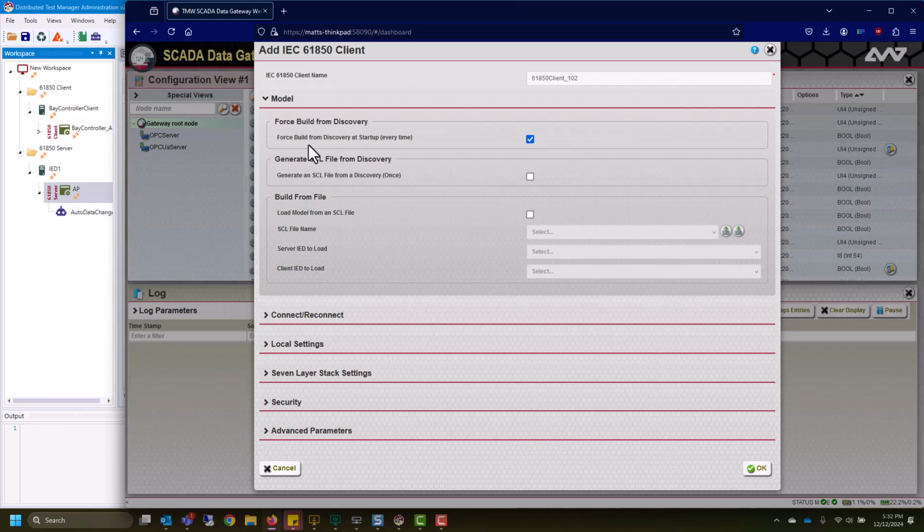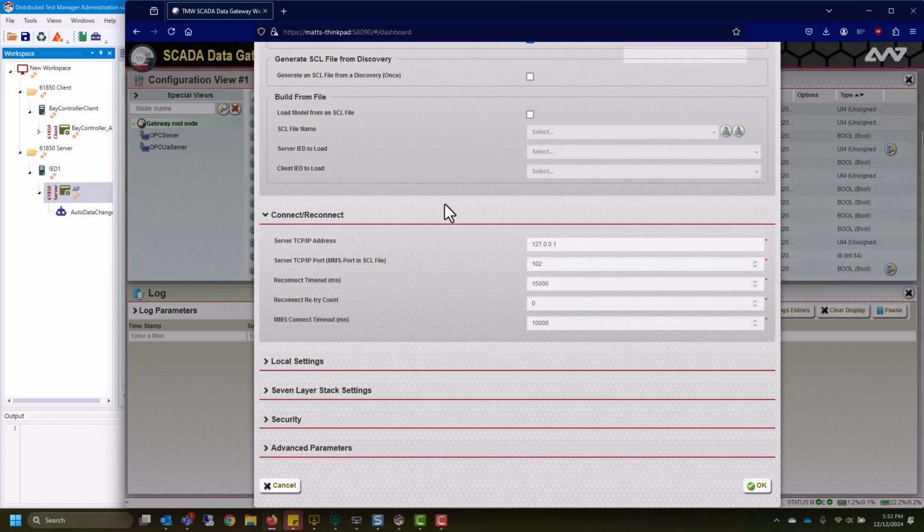I'm going to go ahead and use Discovery on this client so I can walk through that process with you. And then when I create the 61850 server as the database to connect up to the SCADA Master, I'll just go ahead and provide the file and show how that process works. After that, you can go down to each of these sections and update any information as needed.